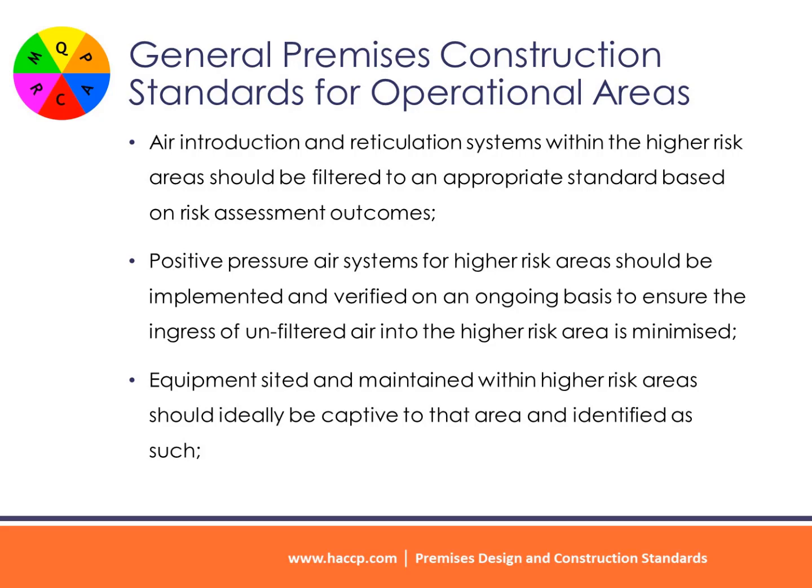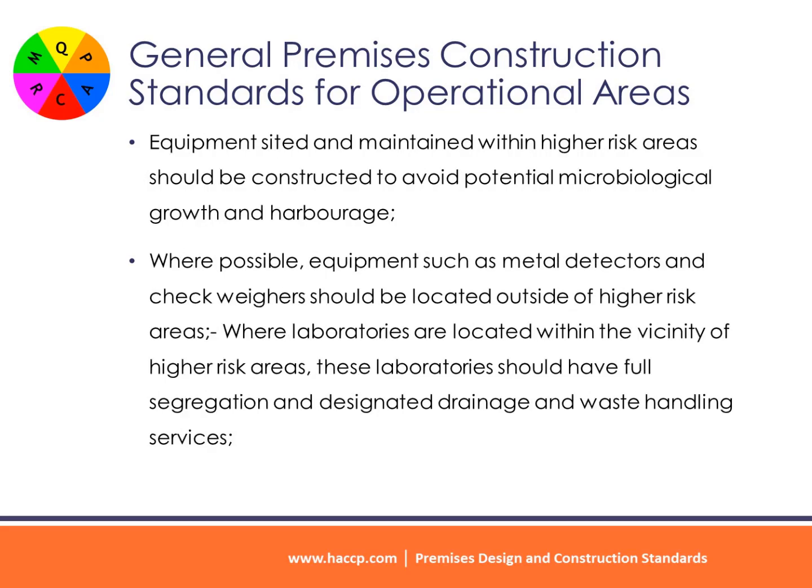Equipment sited and maintained within higher risk areas should ideally be captive to that area and identified as such. Equipment sited and maintained within higher risk areas should be constructed to avoid potential microbiological growth and harborage. Where possible, equipment such as metal detectors and check weighers should be located outside of higher risk areas. Where laboratories are located within the vicinity of higher risk areas, these laboratories should have full segregation and designated drainage and waste handling services.